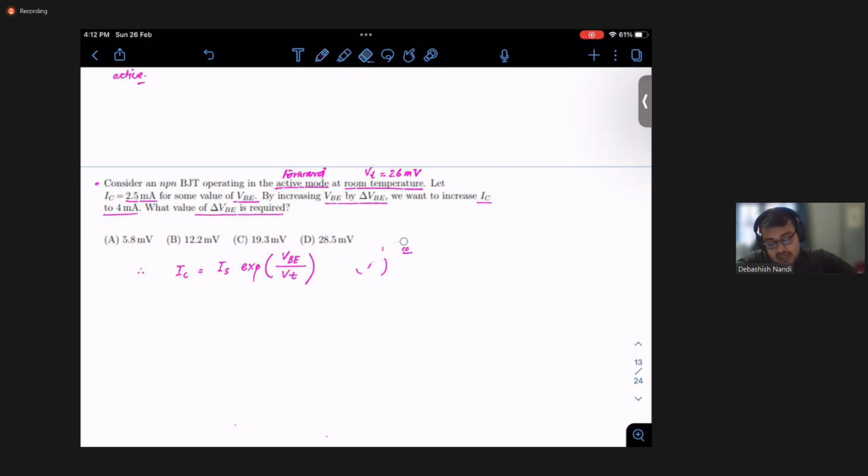So you can write your equation. It is just similar to the diode equation, right? We know the diode equation, that ID is nothing but IS e to the power VD by eta VT minus 1, right? So generally in forward active mode, it is much higher, it is exponentially increasing. So you have the expression.